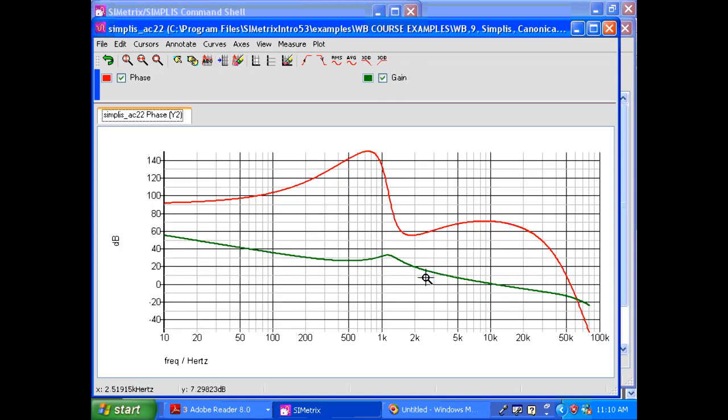Now if you take a good look at this, we're crossing at 10 kilohertz. Good phase margin, about 71 degrees. And a good gain margin down here, but you see no dimple whatsoever. There's nothing around 7 kilohertz. Again, to show you that the impedance of that filter can cause problems. So I believe we demonstrated the impedance mismatching problem to you. You can see how easy that was to do.